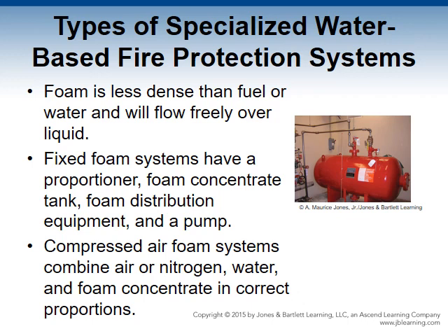Low expansion foams are used to protect outdoor storage tanks, interior flammable liquid hazards, loading racks, dike areas, non-dike spill areas, etc. They increase from a 2-to-1 to a 20-to-1 ratio. Medium expansion foams go from 20-to-1 to 200-to-1. And then the high expansion is 201-to-1 to 1,000-to-1. And you would see high expansion foams in such things as airplane hangars and things of that nature.